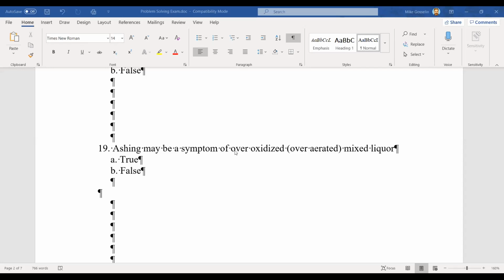If we talked about ashing being, you're going to see a haze in the clarifier, or some start of fine particles, which is going to indicate some other kind of problem that's either happening right now, or that's a looming problem.